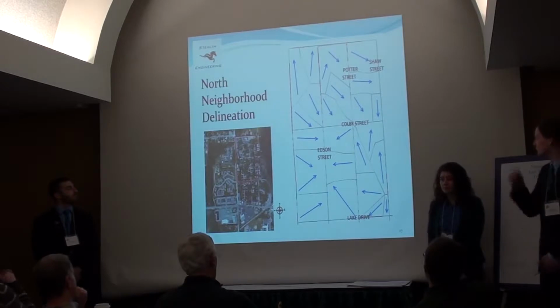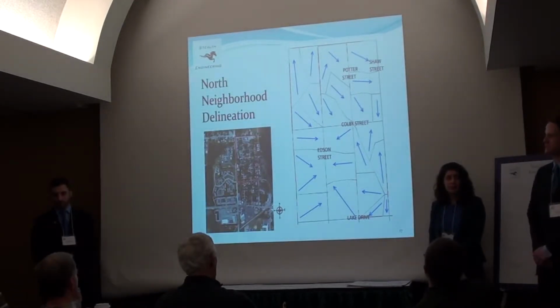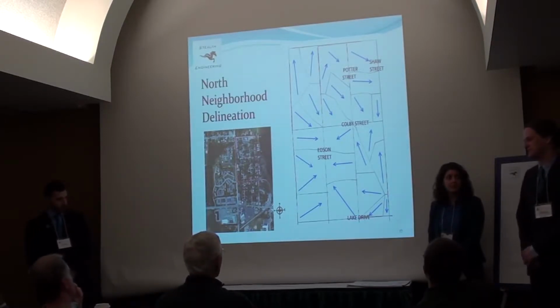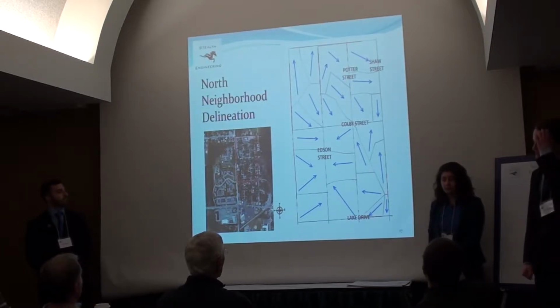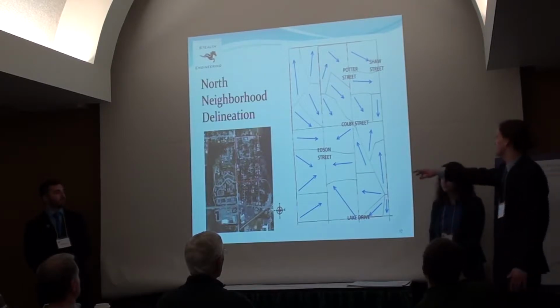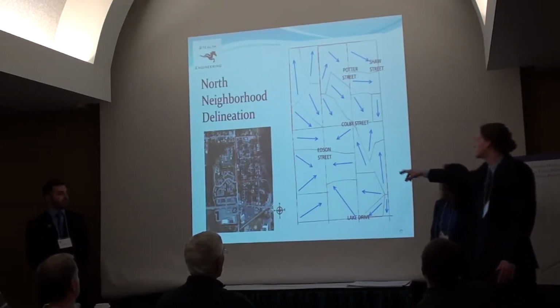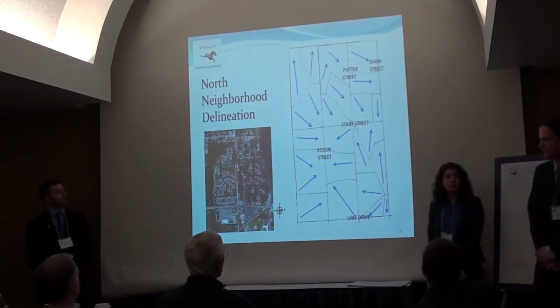And then for the northern part of the neighborhood, we did the same process of finding runoffs and creating sub-catchment areas with boundaries using high elevations and streets. We found out where the most optimal manhole placement is and where flooding problems exist. On this map, throughout blocks between Edson and Potter Street, there's flooding in backyards, and to the north there's more flooding in backyards, so we had to alleviate that.